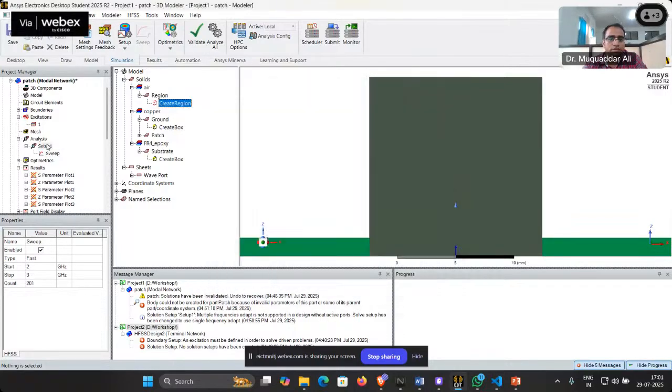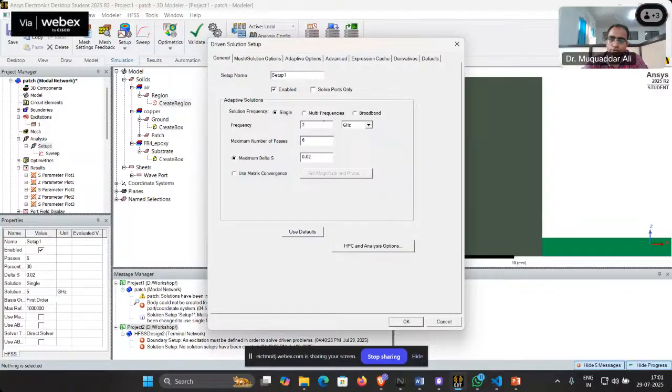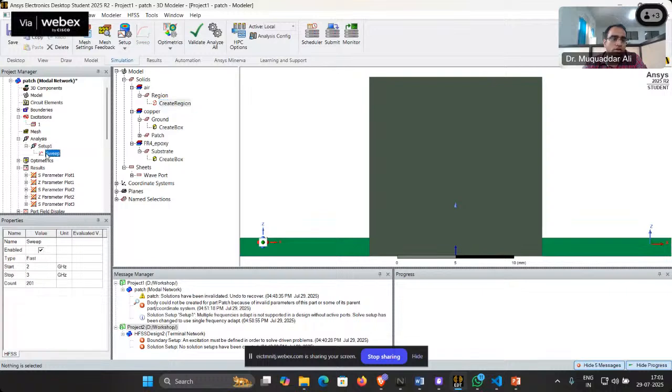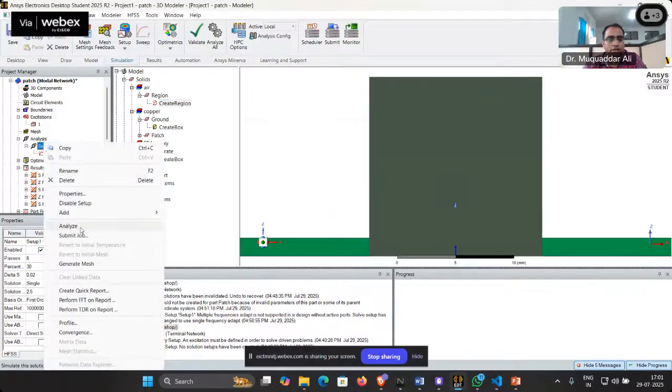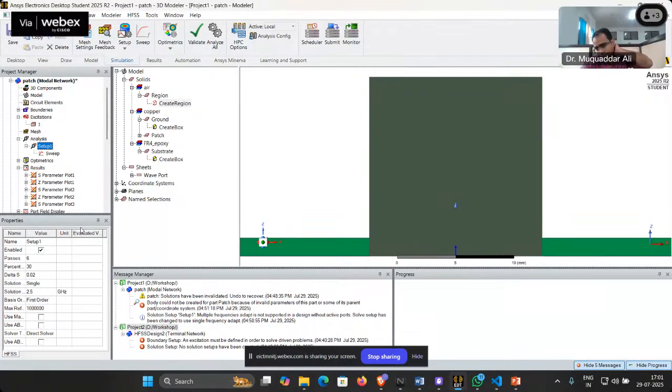So let me reset this analysis setup, it is 2.5 gigahertz. Now validation is okay. Now I select this analysis and right click here and click on analyze. So the analysis is started.